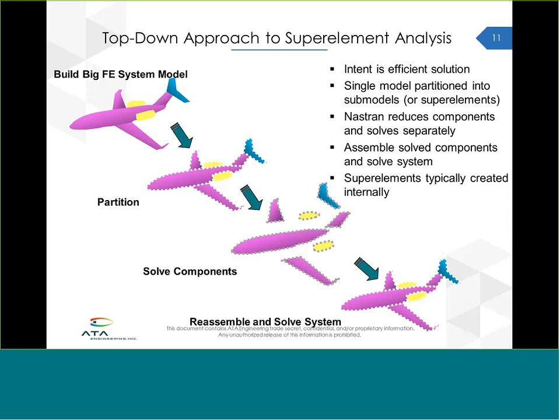If you're running a superelement analysis, the way this works is you first need to tell Nastran what each superelement is, so what parts go within each superelement. That's this second partition image here. You can see you've divided it up into wings, engine, fuselage, tail, all those parts. And once you hit go, Nastran takes those parts one at a time and creates a reduction for those. It takes the wing and says, okay, this wing is a superelement. I know where my boundary degrees of freedom are. It puts everything else aside and creates a reduction of just that wing, whether it's static reduction or dynamic reduction.